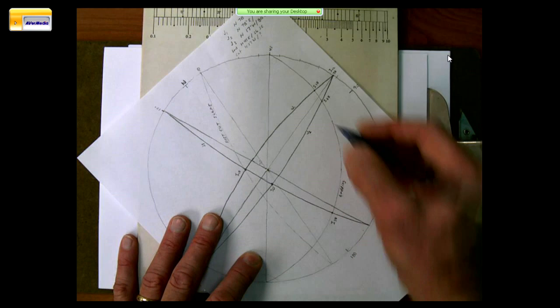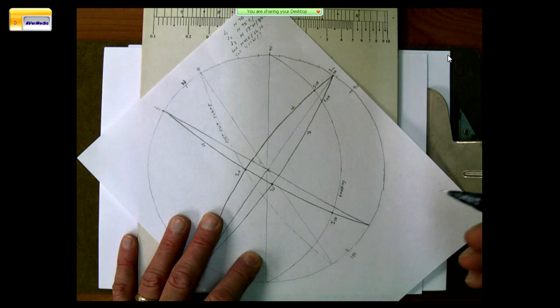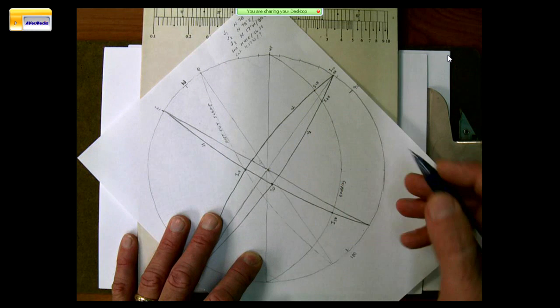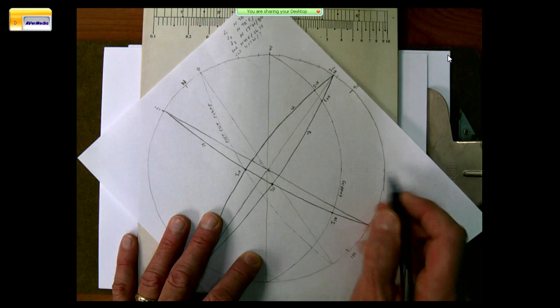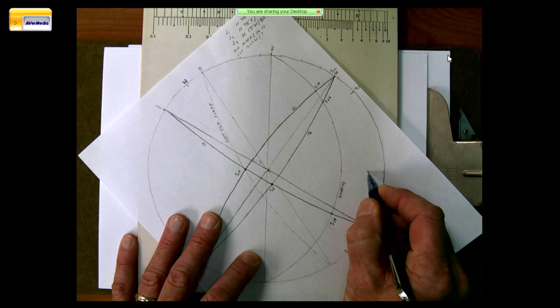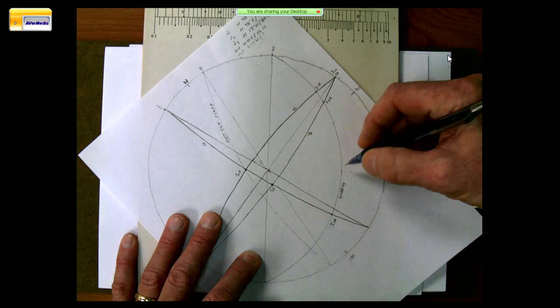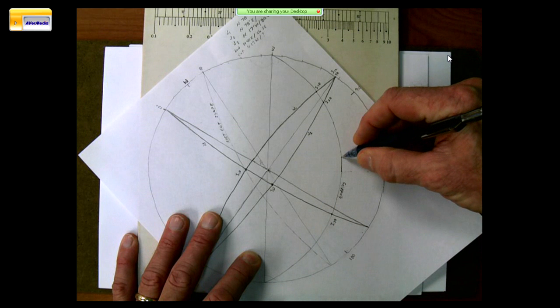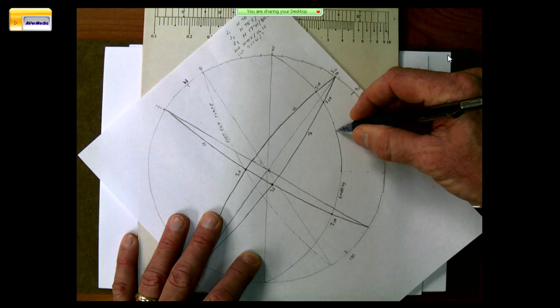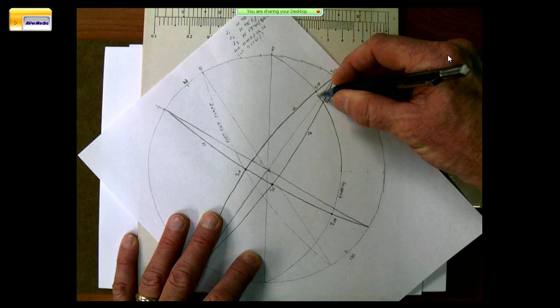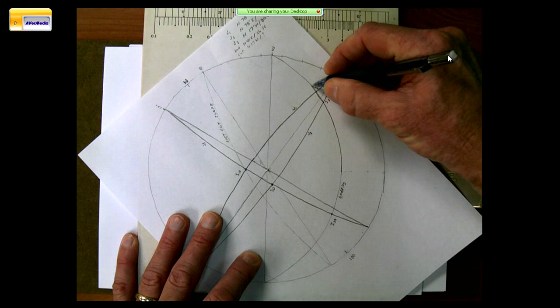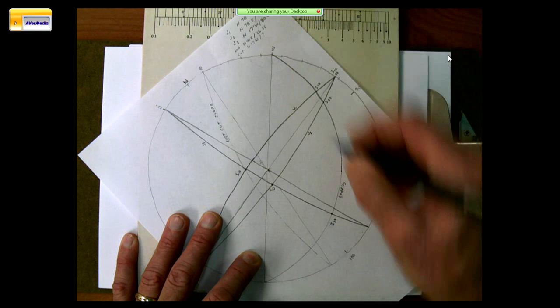And now 26 east is not nearly as severe. So what we're going to do here is we're going to count in and go 10, 20, 2, 4, 6. So here we have a much flatter surface. That's a 2-to-1 slope, by the way, roughly speaking. So we're going to draw this one in, and that's the bedding.